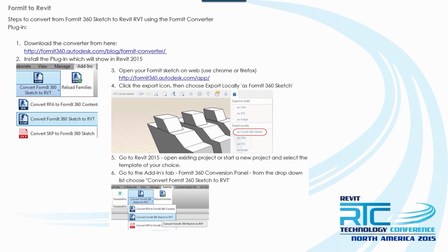When you're building a group, the big thing is to look over in the properties window, and over there you have to give it a name. Once you give it a name, then the category drop down becomes active. That's a little bit of a gotcha. You have to give it a name before you can do that. So just a heads up.